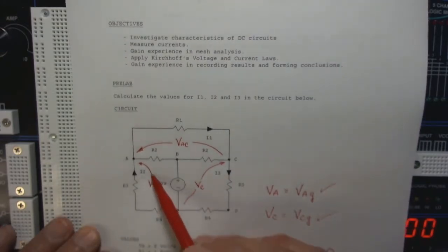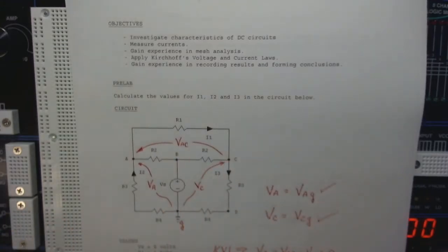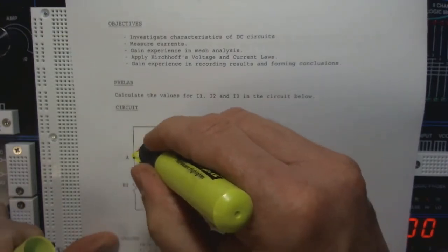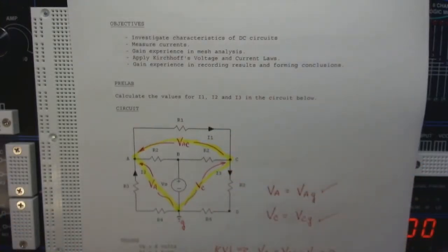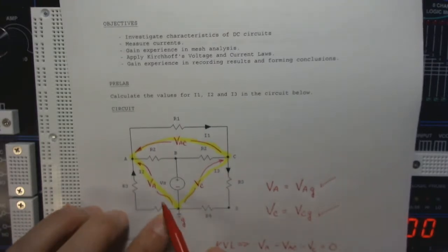So then if you look at this as a path, okay, there I get real fancy, and highlight this path. So I've got a path that looks something like that, right? Okay, that's a closed path. Kirchhoff's law says that the sum of the voltage drops and gains around there is equal to 0. So let's say that I start right here and I go up this way.